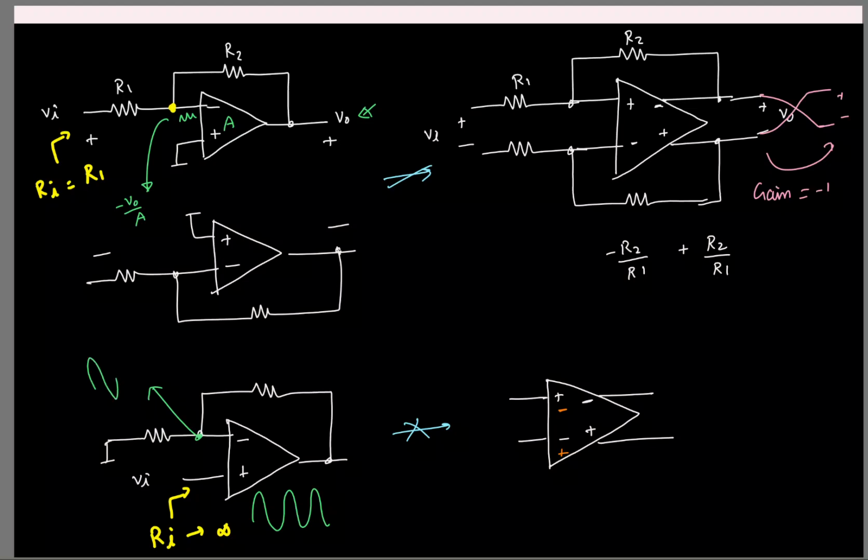So this will also be swinging fully, isn't it? Again, this is going to be connected to the gates of some transistors. So if the gate sees a large swing, what can you say about the transistor operation? Basically, it might not be in saturation, right? It can easily go to linear or cutoff if your swings are very large.